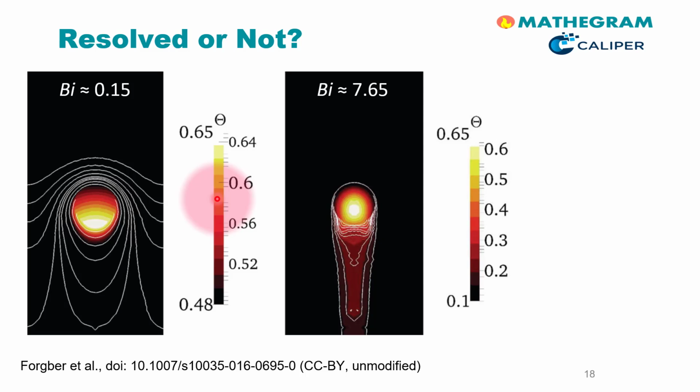Both the fluid and the particle domain are fully resolved, meaning that we used a two-region solver in the software package OpenFOAM. What we see here specifically are two spherical particles, but with different particle conductivities. On the left, a higher conductivity, and on the right, a much lower one.